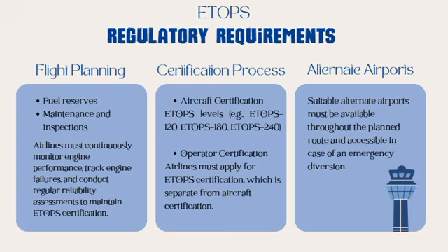And second, the operator certification. Here, airlines must apply for ETOPS certification, which is separate from aircraft certification. This involves demonstrating to the regulatory authority that they have the necessary maintenance programs, crew training, and operational protocols in place to safely handle ETOPS flights. Certification includes audits, inspections, and the ability to maintain engine reliability records.